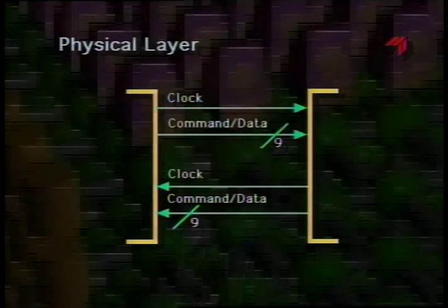Now I'll talk about the physical layer of ServerNet design. This diagram shows the connections between a pair of components communicating through ServerNet. The physical layer has just a total of 20 point-to-point connections, 10 signals in each direction. The cables themselves can be 30 meters maximum length, and shorter cables or backplane connections are used when that length isn't required. The first cables will be shielded twisted pair cables similar to SCSI cables, but later we will also have fiber optic interfaces that extend the distances into the kilometer range.